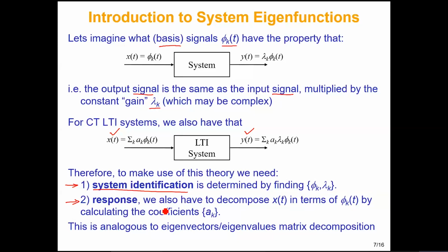Second, we also have to have some way in which we can represent your input x of t in terms of scaled eigenfunctions. And for these scaling factors, we have to have some way of computing them. So we have to have some way of representing your input signal x of t in terms of a scaled sum of eigenfunctions, and we need some way of finding out what all the scaling factors a_k would be.